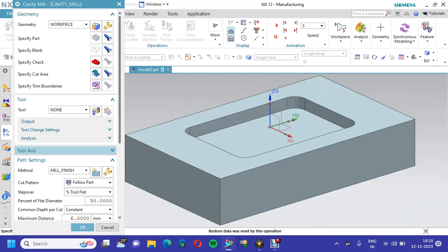But in this case, I am taking the exact size of end mill, dia 10. Both I will use for roughing as well as finishing operations. I am going to use two operations, one for roughing, another for finishing. For finishing, I will do rest milling. In rough milling, I have given 1 mm allowance for finishing purpose. The finishing purpose is my rest milling.